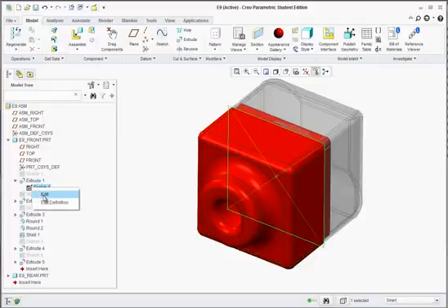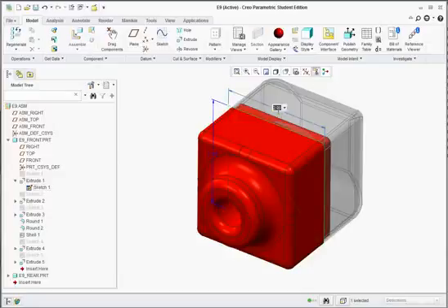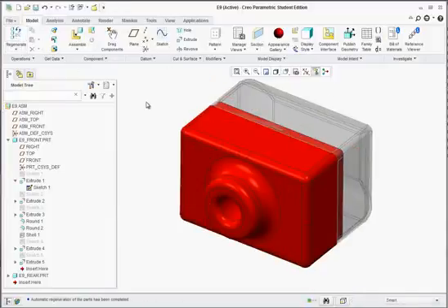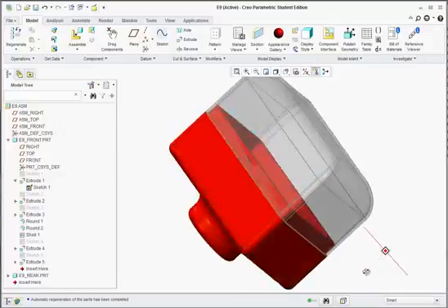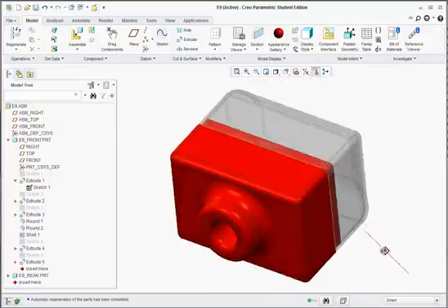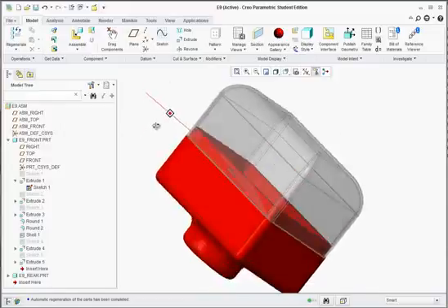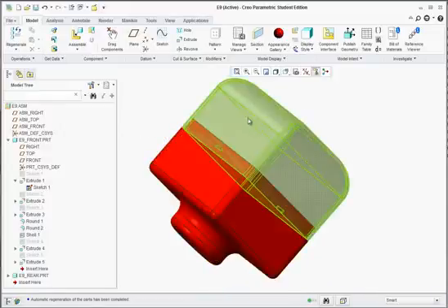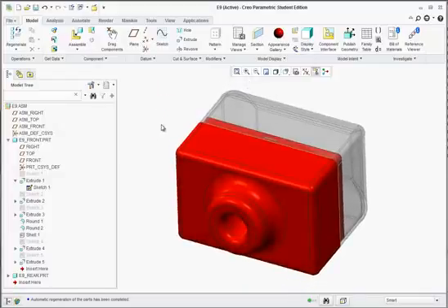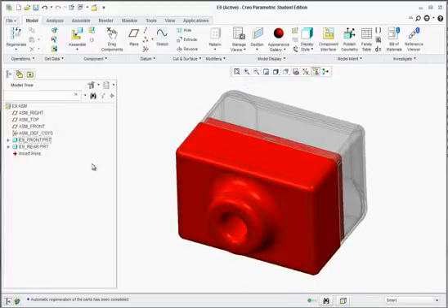If we edit that, we should get the dimensions that appear. We didn't have to edit definition, we just went to edit. And let's say we wanted to widen this. Double click on this 2, we'll make it 3. Okay. Now we're going to have to regenerate. And they both should update just like that. If not, hit regenerate a second time. And that is the power of top-down assembly modeling. You change one part, they both update. And yet they're both separate parts, E9 front and rear.